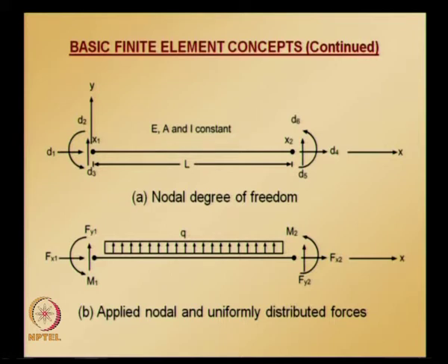D1 and D4 are the degrees of freedom corresponding to the axial deformation, D2 and D5 correspond to the transverse displacement, and D3 and D6 correspond to the rotations.